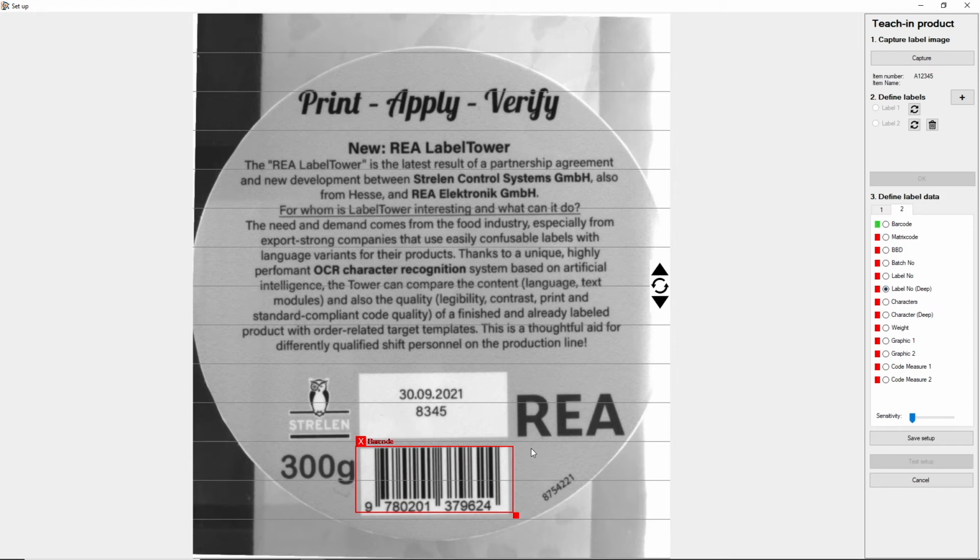I place a frame somewhere in the image, move the pointer to the degree display, hold down the left mouse button and move the mouse upwards. With this, I can rotate the frame until it has the same orientation as the text. Now I can position the frame correctly and adjust the size.